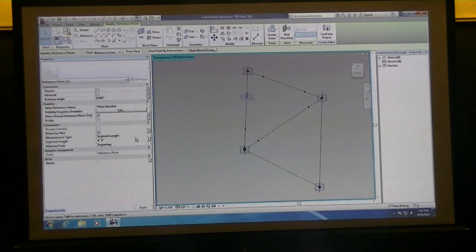But if we set our parameters to particular lengths, let's say I want this point to always be 4 feet away from here, we run into trouble when we start to divide up a surface, because we don't know what the end lengths are going to be of all the divided grids. You could run into a situation where you've told the computer to move this point 4 feet away, but that line might only end up being 3 feet, and you'll get an error.